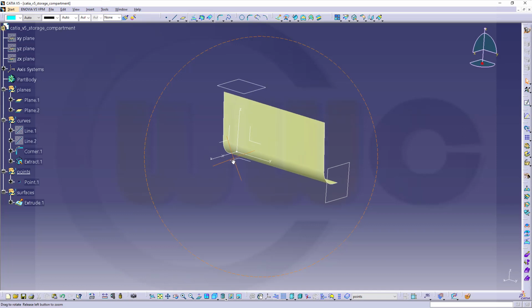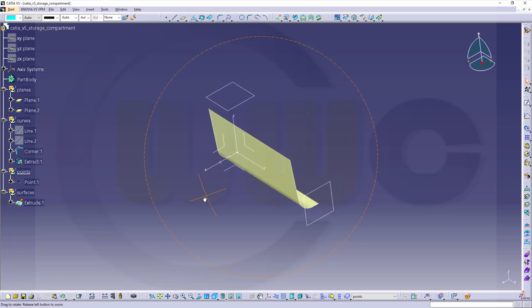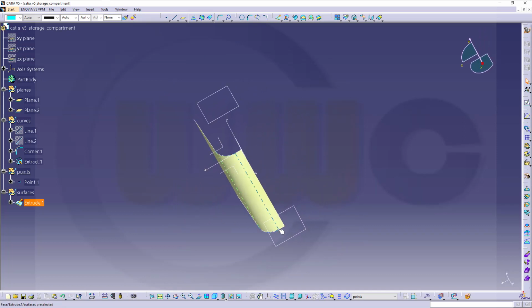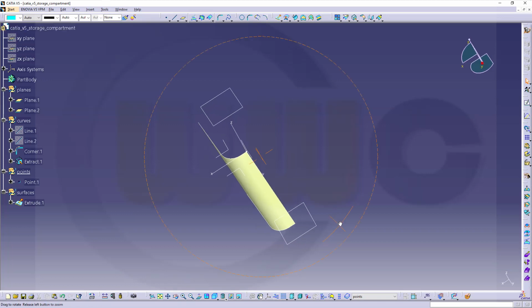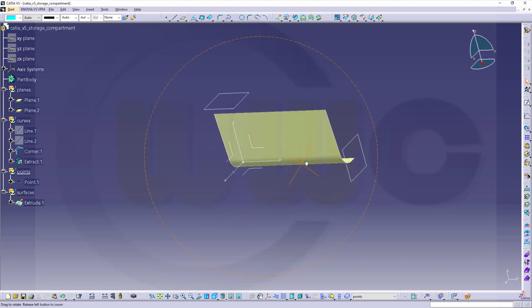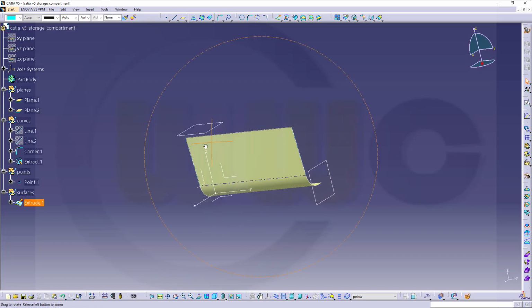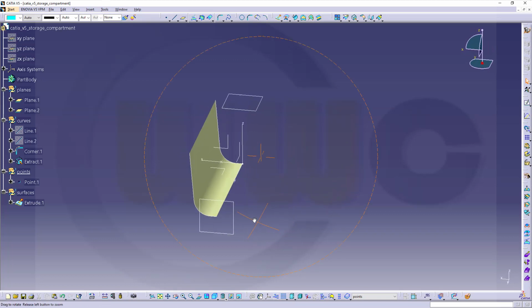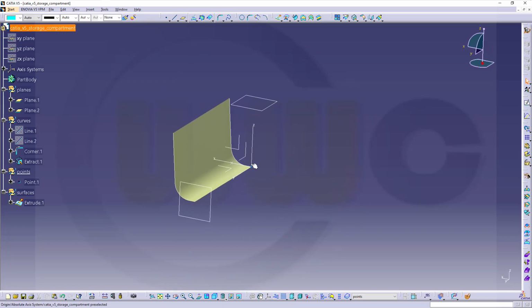I need an arc with radius 60 millimeters here and there, and it should go tangent into that edge, and therefore I need a center point, and that center point would be in this case somewhere over here, about that.